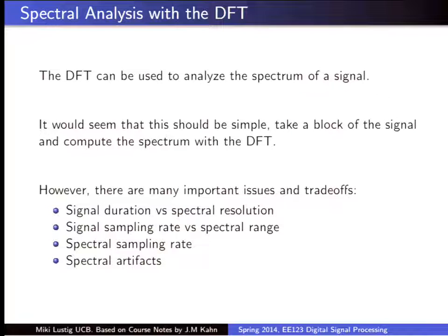You compute a spectrum, and we also want to represent it on the computer. We're going to discretize the spectrum as well. So we're going to approximate or sample the DTFT effectively when we display it. We're not going to display it continuously, right? And then we're going to talk about some spectral artifacts associated with the fact that we are taking things over a finite time. There's no such thing as a pure frequency when we're talking about finite time, because it changes.